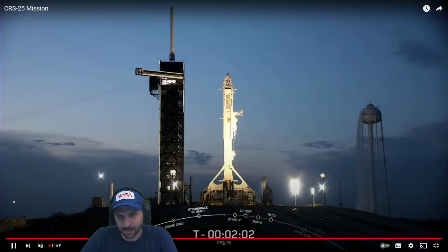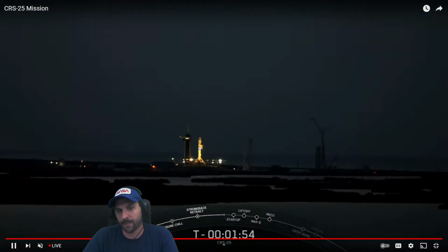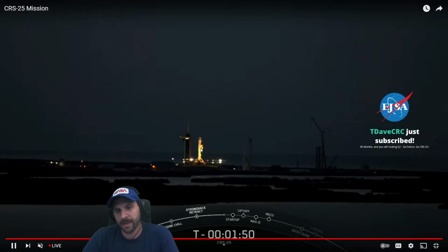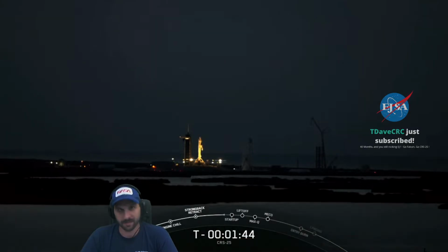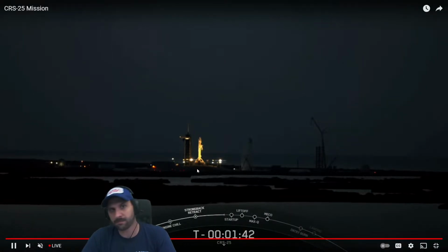They will do a gas closeout, and what that gas closeout basically entails is pumping nitrogen gas up the fuel lines, and then they open up a valve at the top. They obviously close the valve off to the second stage. And then they open up that valve on the side, and the transporter erector will, as the kids say, rip a fat vape. Yeah, it should be happening in the next minute or so.